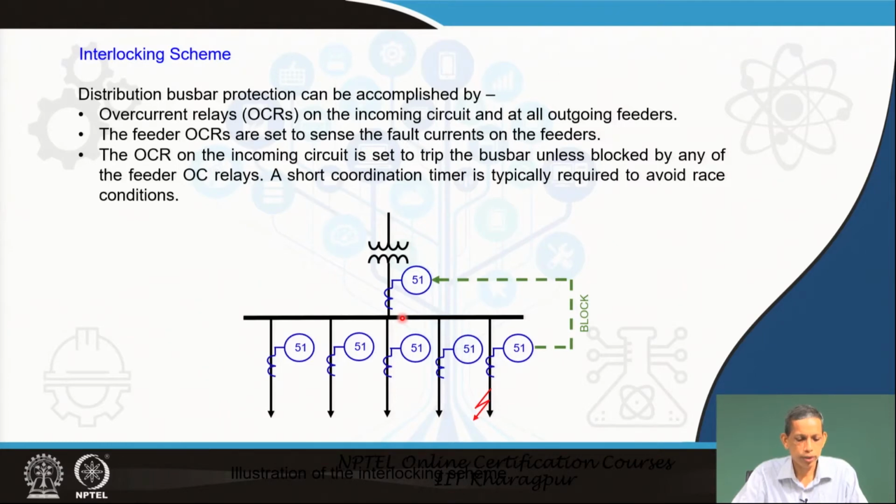Only one point here is that a short coordination timer is required between the outgoing overcurrent relays and the incoming overcurrent relay.